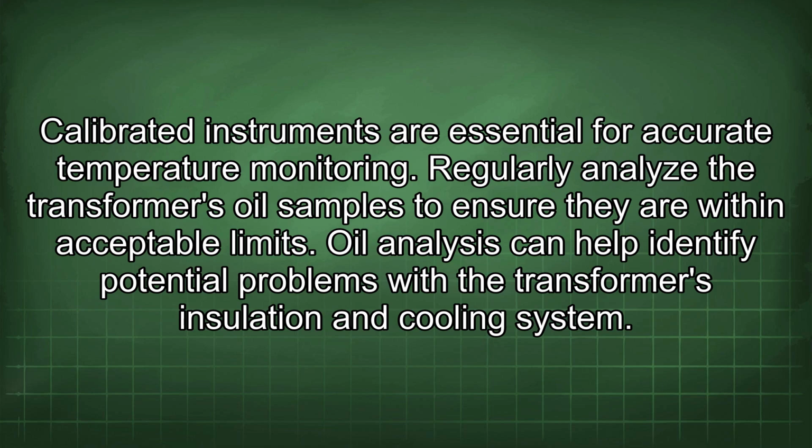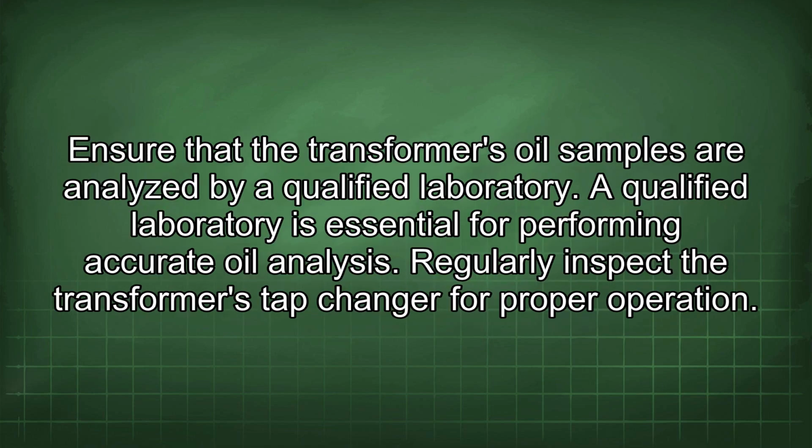Regularly analyze the transformer's oil samples to ensure they are within acceptable limits. Oil analysis can help identify potential problems with the transformer's insulation and cooling system. Ensure that the transformer's oil samples are analyzed by a qualified laboratory. A qualified laboratory is essential for performing accurate oil analysis.